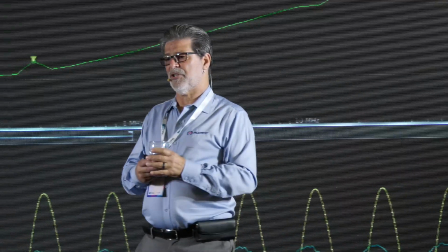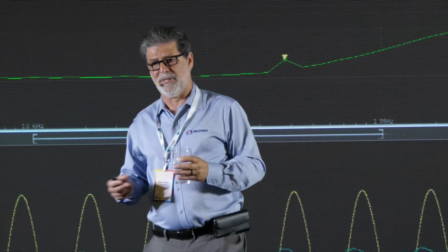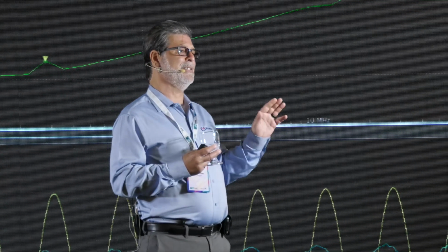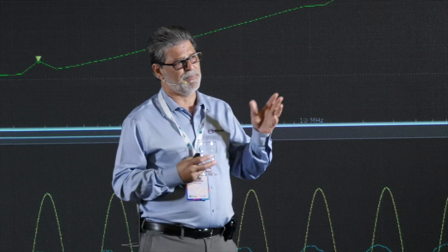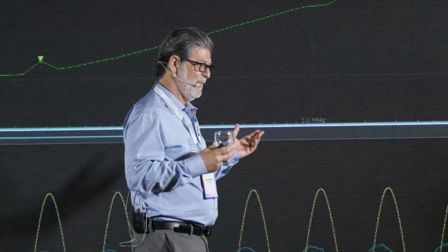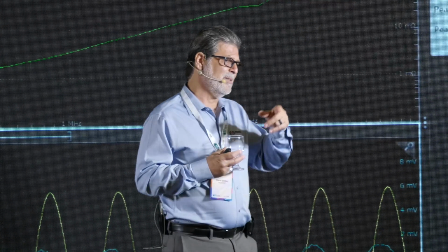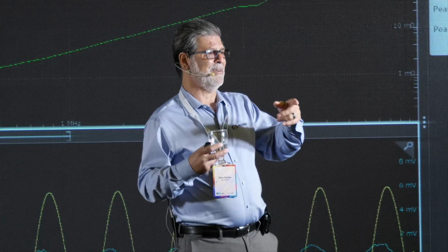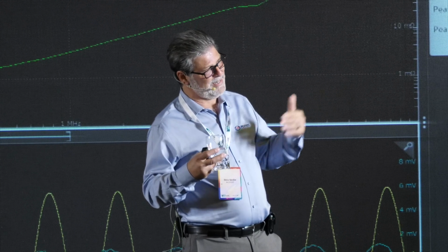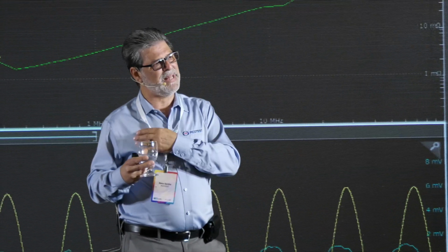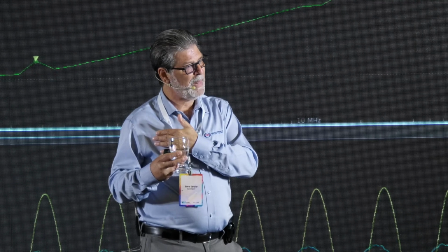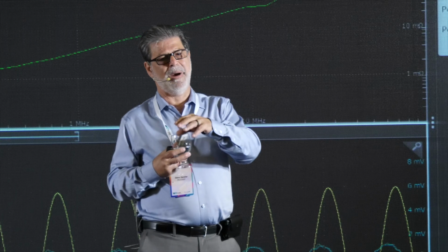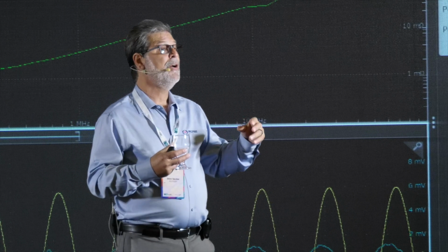My wife comes out of the store and she says, I'm ready to go, and I start the engine, and while the engine is starting, the battery bus is not 12 volts anymore. Now it's bouncing between 5 and 60 volts. Huge transients. Do I still need to meet power integrity? Of course I do. Now I got to meet power integrity with a 55 volt transient into the power supply. Of course some of that is going to leak out.